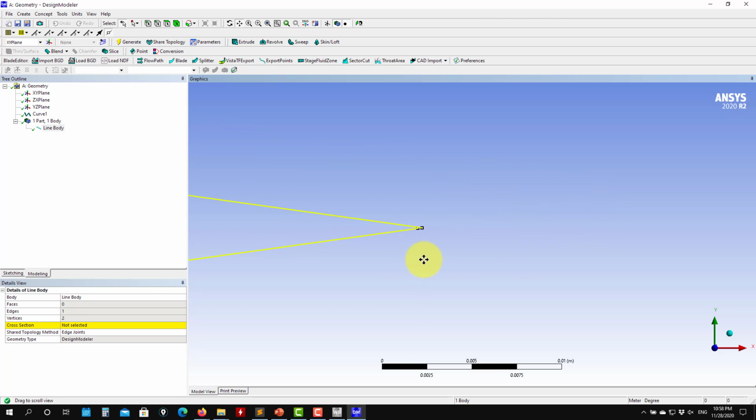But let's zoom here. See that you have a small gap there, so it's not closed. You can imagine that because here you are creating a kind of spline, if you close it, it will give you an error, so that's why you cannot do it. When you import it, it will give you an error, so do not close one single curve. If you choose to work this way, you can now close it manually.